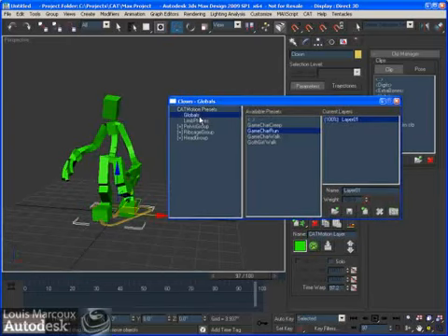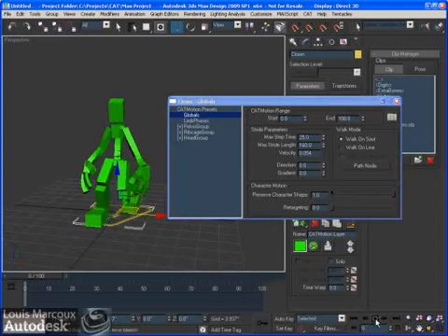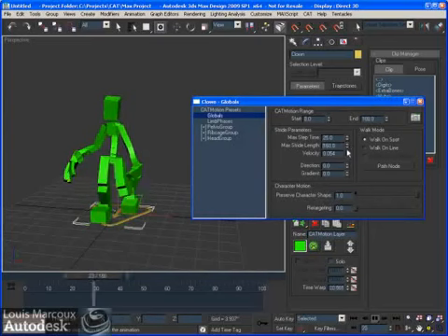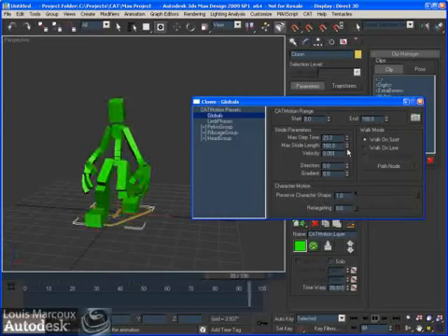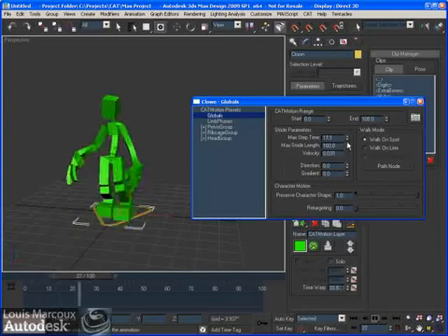And what I want to show you is some of the settings. So I'm going to go into globals first. This is the step time. This is the stride length. You got the velocity, and all of these are related to each other. Which means that if this character is walking at this speed and I want the character to walk a bit faster, I'll just reduce the step time. And you see that here the velocity is kind of increasing as well.